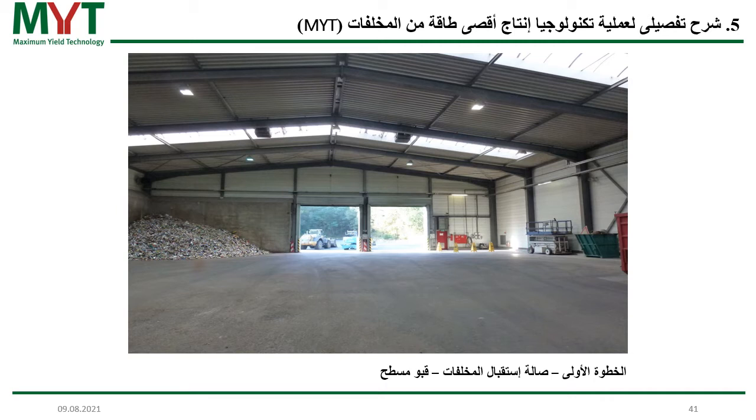So when the trucks come in and unload, they put this waste on the flat bunker, and then it can be inspected. And if there are, for example, motor blocks or big trunks inside, which we already had, we can exclude these big parts here and treat them separately, because if we would just put them in the system, they would block our process, they would harm our components, the sieve drum for example, and then we would have increased maintenance and also costs. So we work with a flat bunker here to see what is inside the waste.